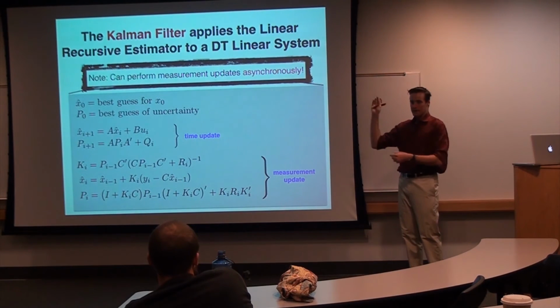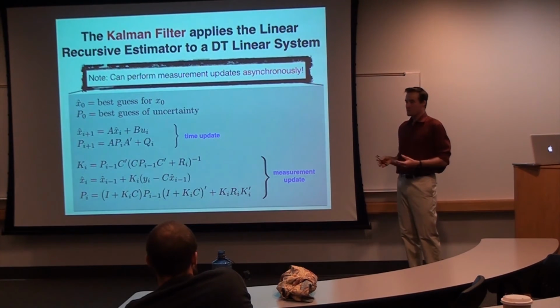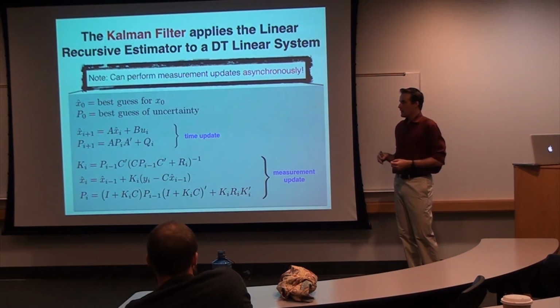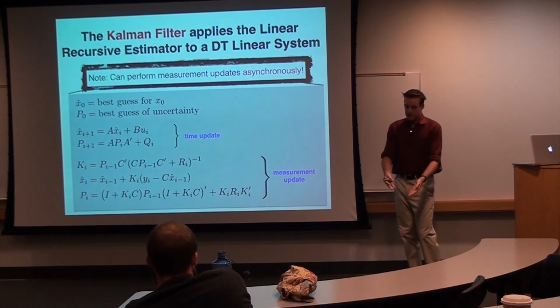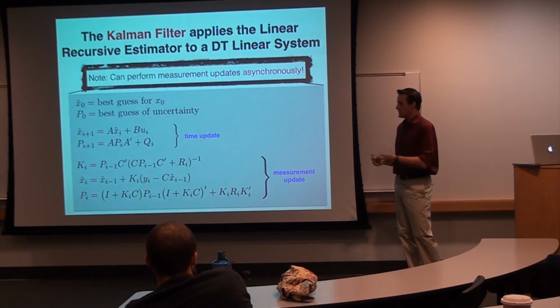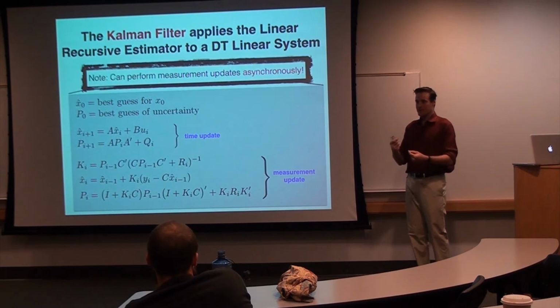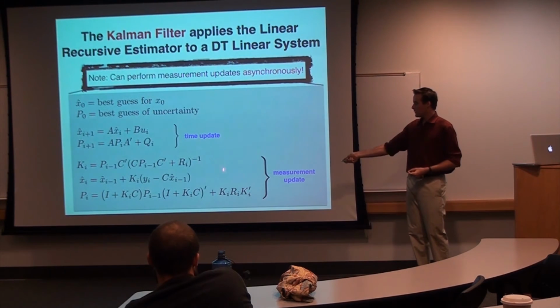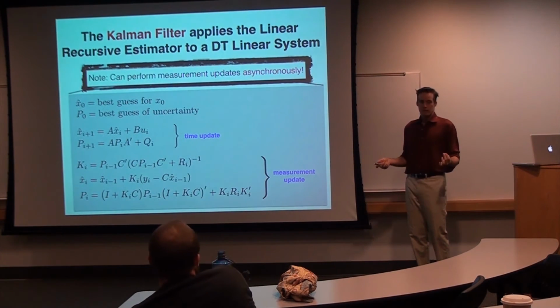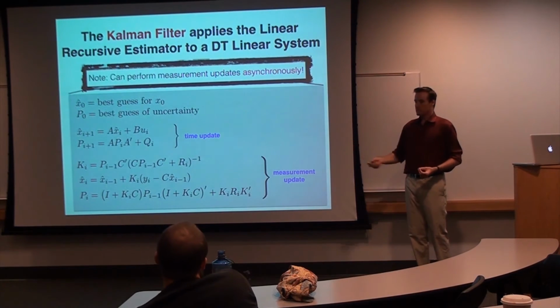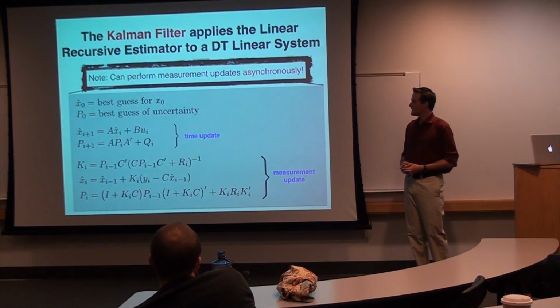We had these little hand-launched remote-controlled drones that the Army was using for reconnaissance, and they were running an autopilot that was updating its estimate of the state at 100 hertz. It had a 10 hertz magnetometer, a 1 hertz GPS, and a 50 hertz accelerometer, and all of those could be updated on an asynchronous, ad hoc basis according to these equations that were totally decoupled from the propagation of the state in the first place.